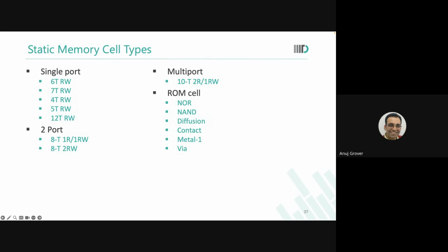So what happens is that if you are programming at the diffusion stage, then what will the fab do? They will fabricate until P well and N well. And then wait, tell me, where is active, where is it not? So they just prepared the wafers and now are waiting for you to get to the next step.